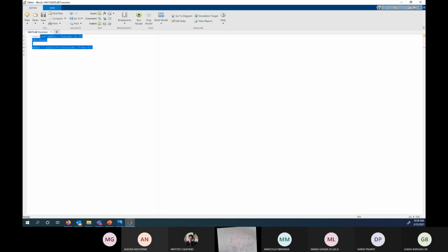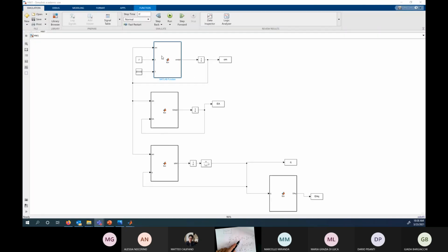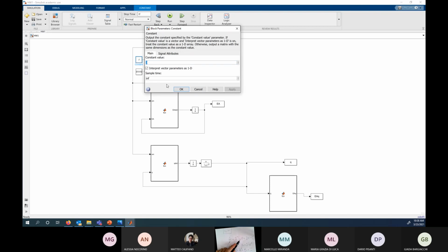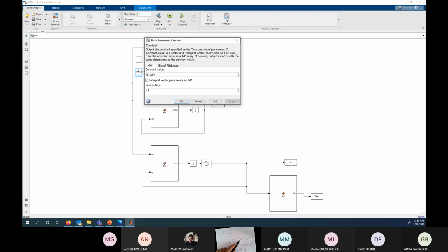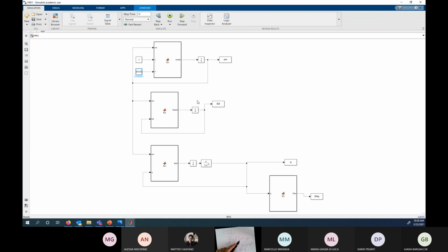So if you look at this function here, it is taking as inputs everything that I see on the right-hand side. On the right-hand side of my expression, I have omega, J, and the external torques, and the output is omega dot. So this is in general how you want to do it for any differential equation in Simulink. This block in Simulink is taking as input the angular velocity, your J matrix, whatever that is, and your external torques, whatever they are. In this case, I'm just giving 3 zeros. And it's spitting out the omega dot.